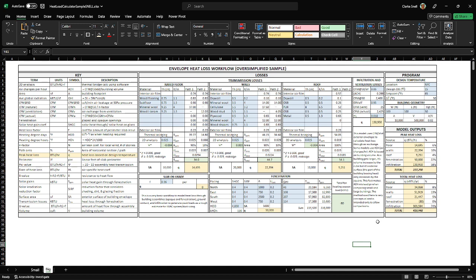If we pressurize it, in other words, we change the pressure so there's air pushing into the inside or the outside of the building, we define that per square foot. So this is 0.06 CFM 50 per square foot. Now, this is a high performance building setting. You could look up different ones or just leave this one. It's basically how we're designing the building to perform. We're saying we want this building to only lose 0.06 cubic feet per minute of air at 50 pascals per square foot. Then we calculated the air exchanges per hour.